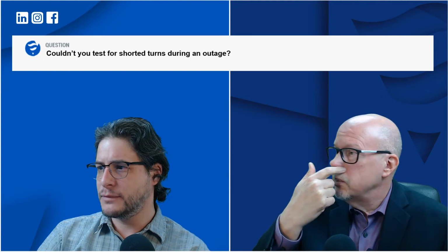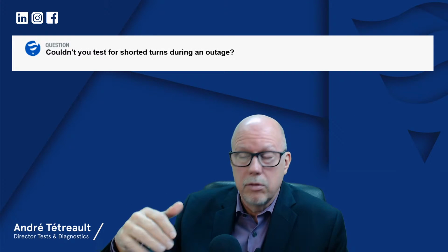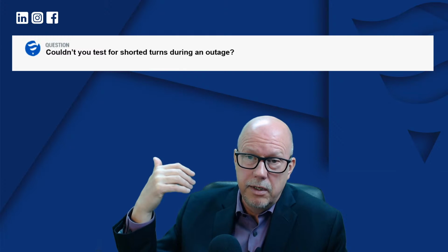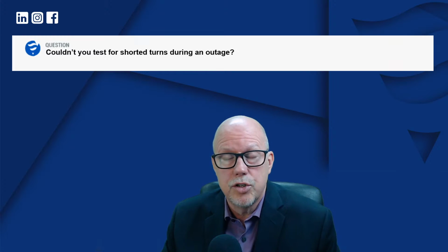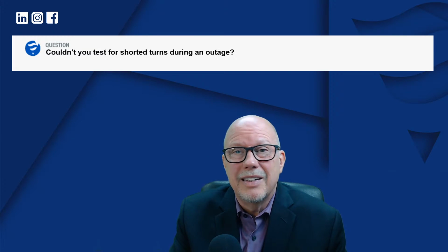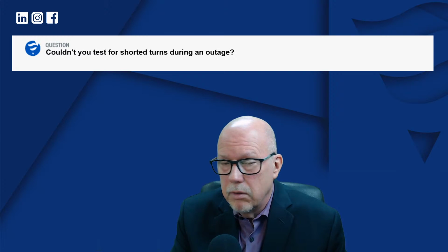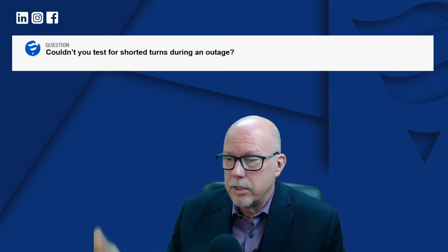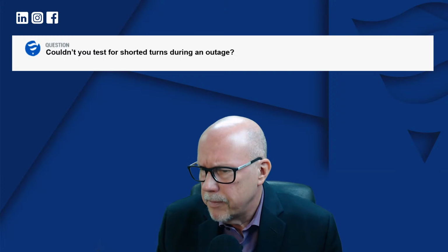As I mentioned previously, in some cases, people notice that if they increase the load, the shaft vibration goes up, and in some cases, they realize that they need much more rotor current to produce the same amount of VAR, so they suspect that there's an issue with shorted turns. And what they would do is do testing on the unit while the unit is stopped. There's all kinds of tests. One of the most popular ones is a recurrent surge oscillation test or an RSO test. And I think you can actually do them with the unit rotating.